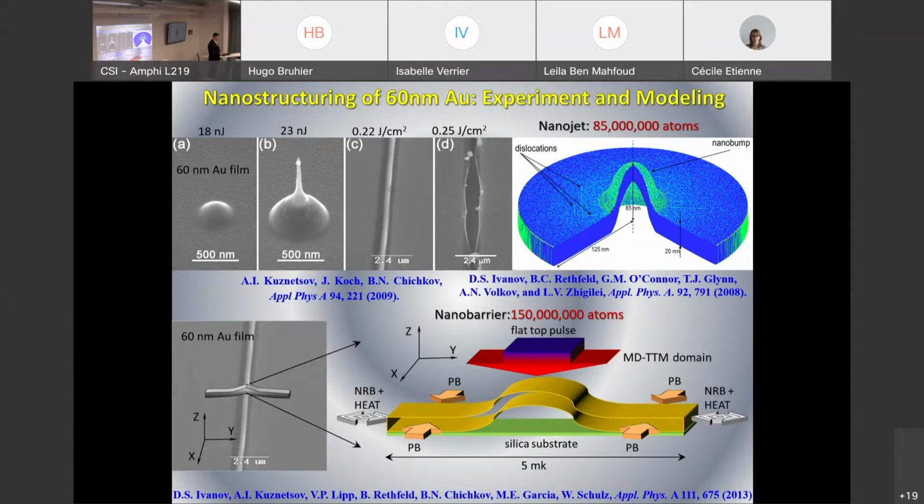For that purpose, we take this elongated brick of material. We also realize that there is no temperature or pressure gradient in one of the directions, the x direction. So we have this computational cell, schematically shown here. We have a molecular dynamics domain situated on a silica substrate covering 5 microns of experimental scale. We model only 5 microns with the combined model, and then up to 50 microns away we provide a heat flux, but described in continuum because no phase transitions occur at this distance.